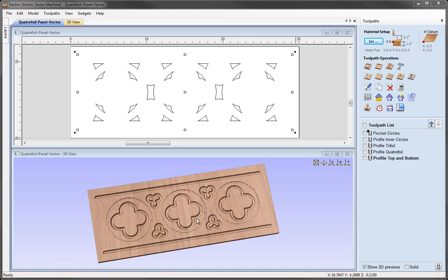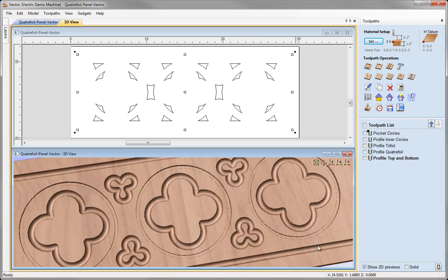One useful feature to point out, if we zoom in here, at the bottom of the interface, just below where the cursor is at the moment, you can see there's an X, Y and Z coordinate being displayed, and that's showing me the position of the point of the cursor. As I move that over an area we've cut in the 3D view, it shows me the Z depth of that area. This is very useful if I wanted to eyeball, for instance, the area that we'd pocketed out and check its Z depth, and I can see there it's showing me a Z depth of -1/8 of an inch. So again, just a quick way of visually checking the depth of something. If you want to, point the cursor at it, and at the bottom of the interface there, it'll show you the coordinate of the area you're pointing at.